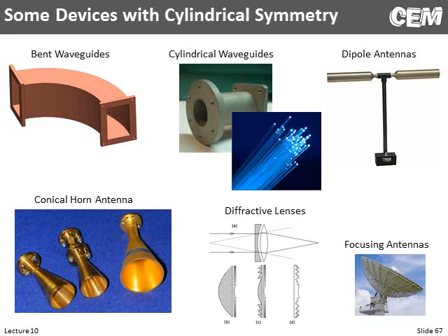So that's it for this lecture. The key thing to come away with was how we took Maxwell's equations, we approximated all of the derivatives using finite differences, but placed the fields on a Yee grid. And the Yee grid let us implicitly satisfy the divergence equation so we don't have to handle it. Physical boundary conditions are handled, and it was a very elegant relationship to do finite differences. And we ended up with the smallest possible equations with the highest possible accuracy by staggering our fields that way.